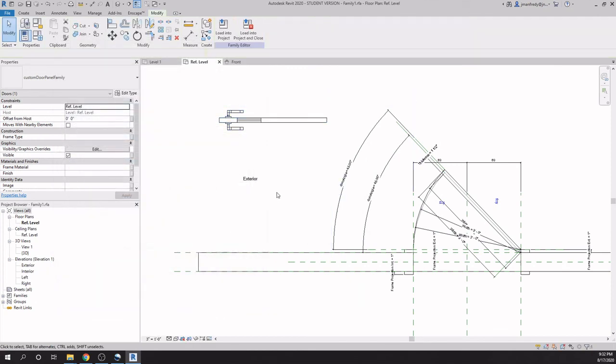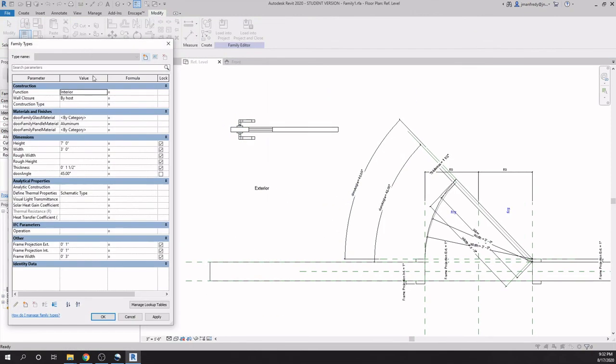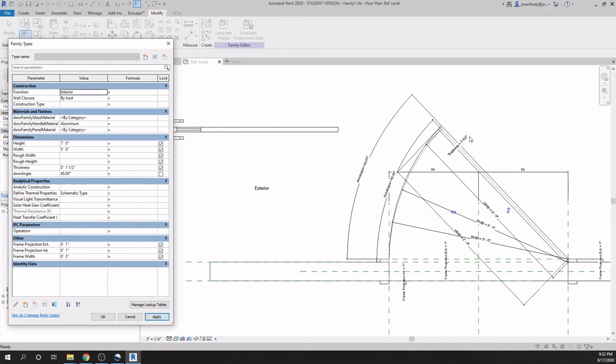Hit apply. So now you'll notice that when I go to parameters here and I change these settings, it won't only change the opening, it'll also change that family because those settings for that door are now associated with these settings. So as this thickness becomes a foot, you see the door gets quite large here in the drawing and obviously here. We know that's perhaps 1.5 inches. That parameter is working. This door becomes 5 feet long. Notice that it becomes 5 feet long here, but this drawing also becomes 5 feet long because they're now working together in tandem. So this is all functioning properly.